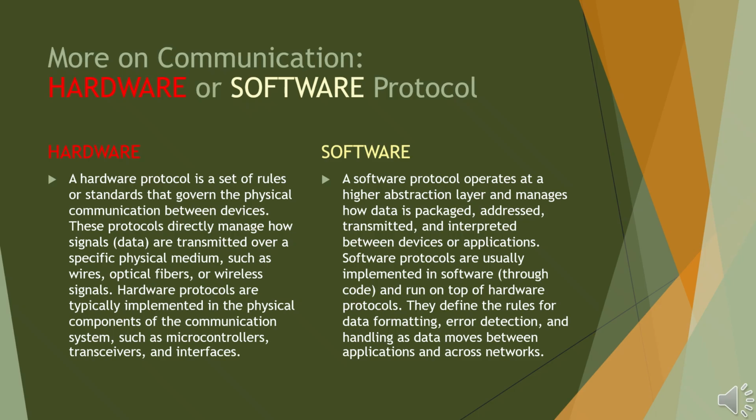In other words, how signals actually travel through wires or connectors. It deals with details like voltage levels, for example, 0 to 5 volts in TTL logic, plus or minus 12 volts in RS-232, or differential signaling in CAN and Ethernet. Timing and synchronization, how fast data bits are transmitted, baud rate, clock cycles.